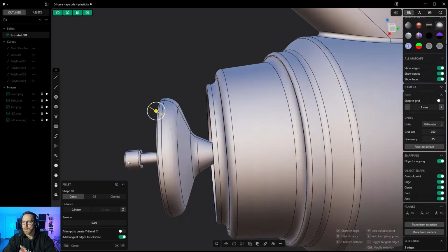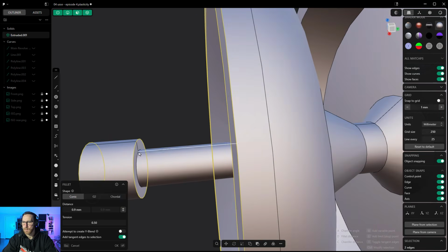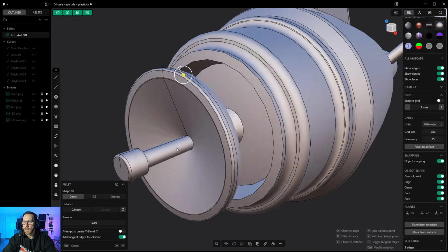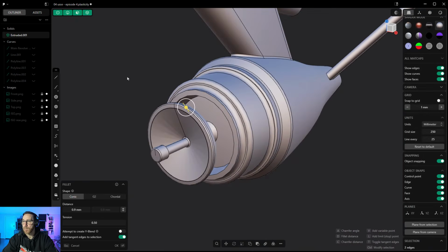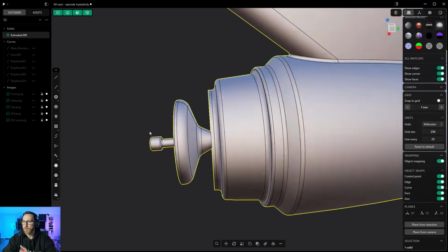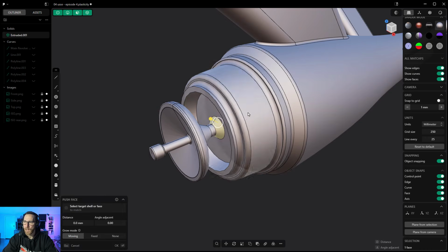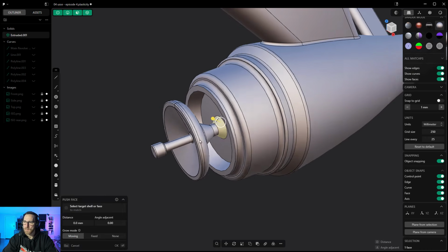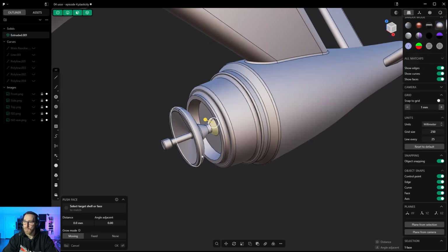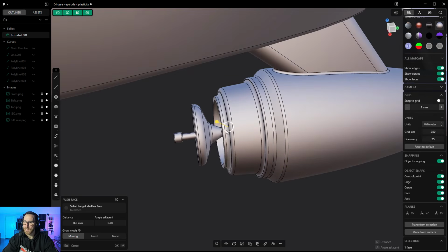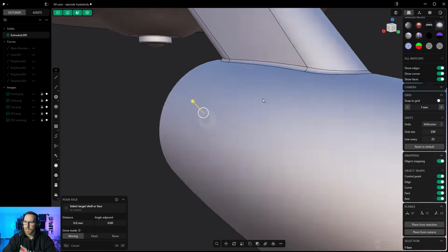And so let's rotate this around. And again, if we were designing this for, let's say, 3D printing, at this stage we would want to be really careful with geometry like this. A part like this likely would be printed by itself afterwards and then assembled, glued together, whatever the case might be. So I would essentially take a shaft that goes deeper into this and then print this on its own. You could likely get away with printing it in the Z direction.